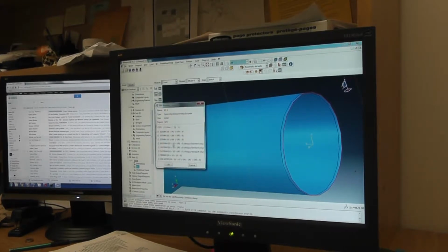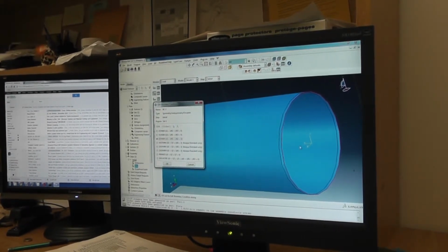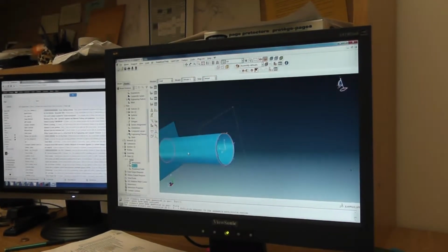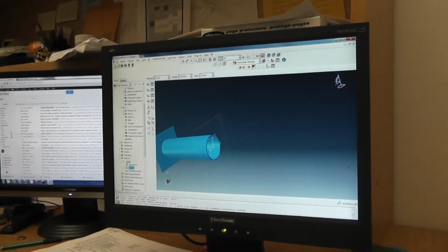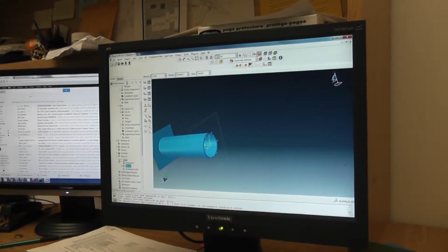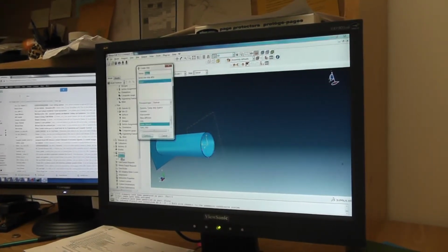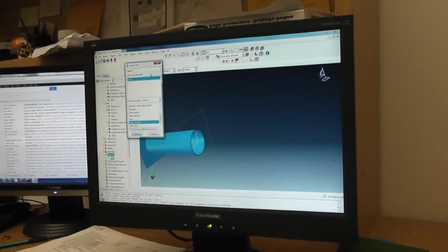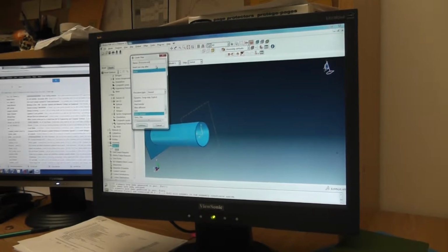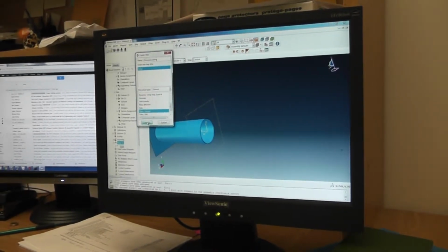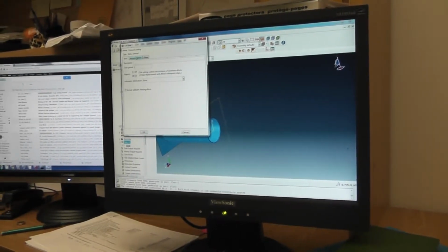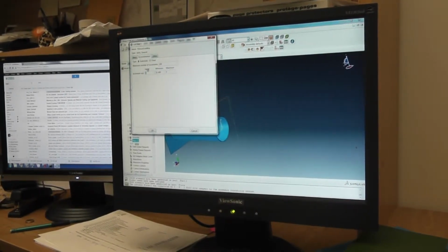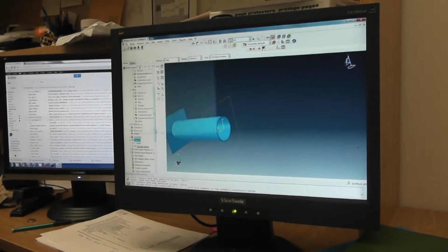This has a Z sim because it's a plane perpendicular to Z. And now this boundary condition will always be there. Now I'm going to create a new part, new step, loading or pressure loading. I always like to keep nonlinearity in the geometry on. Let's keep these as is and let's see what will happen.